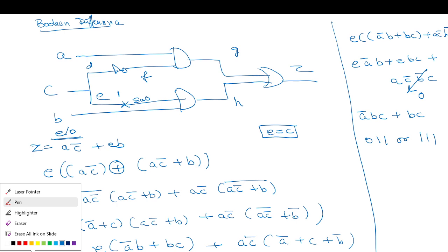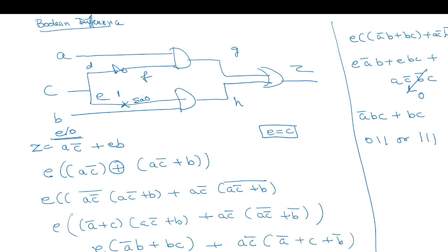Let's do this through our method. Now to justify this, we want a 1 here, a non-controlling value here. So here the value will be 1 by 0, which is D. So at the output we want either D or D bar. So this should be a non-controlling value. We have a 1 here, so it is automatically 0 here. So this can be don't care. So we have obtained the requirement.